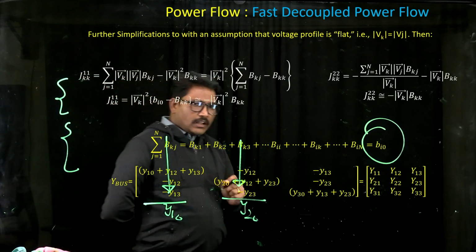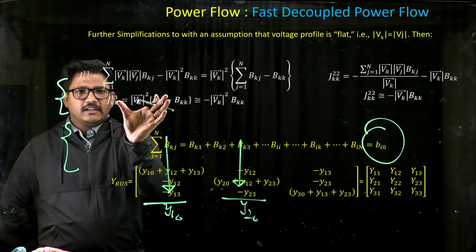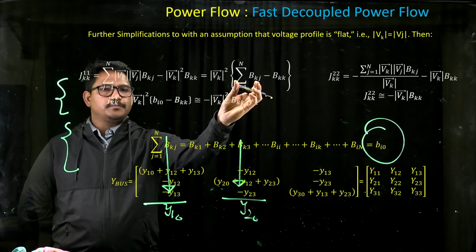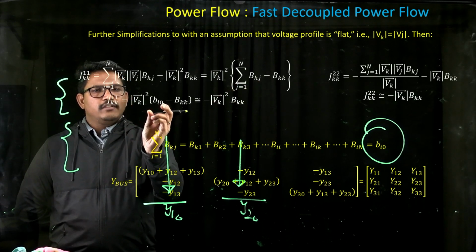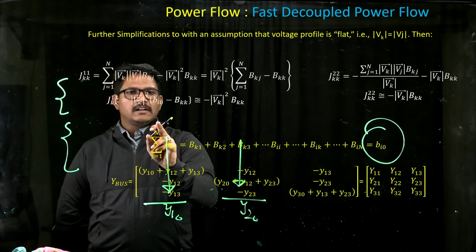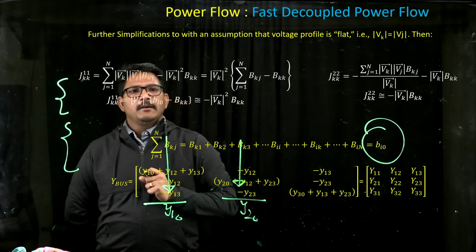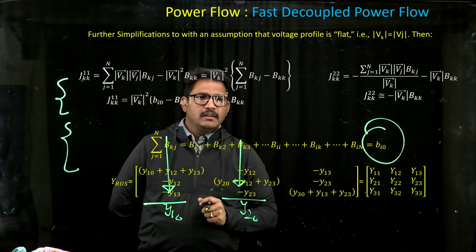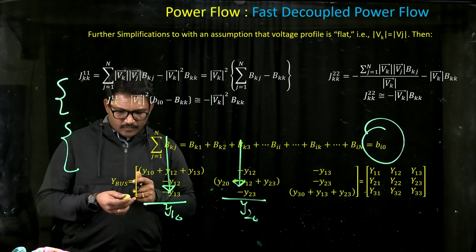Now, if you look at the shunt susceptance in relation to the diagonal elements in the admittance matrix, that is where you have this expression where the first value is small BI0. Now you know that small BI0 will be much smaller when compared to BKK, so we neglect that BI0. As a result, we'll have this expression as minus VK square multiplied by BKK itself. Similarly, we'll also have the diagonal element corresponding to J22 being simplified with the same assumption.